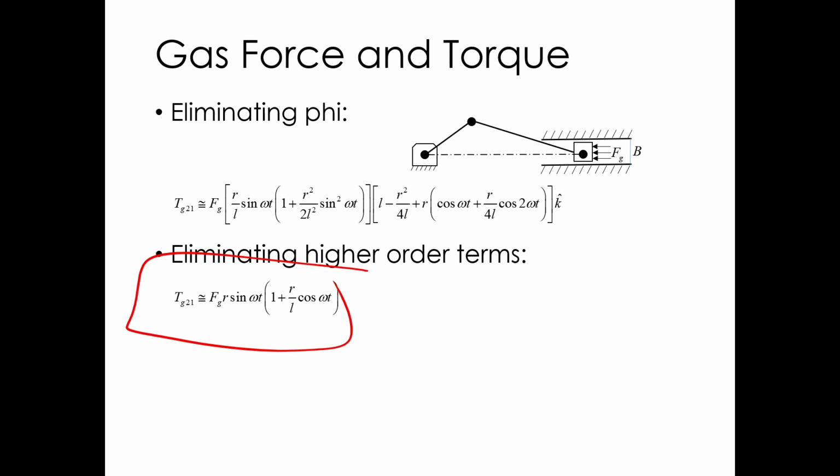So at this point in time, if you want to do a better job, rather than trying to keep refining this approach, go back to force analysis for a crank slider engine and the equations we derived there, and you can use that to create a really good free body diagram based model where you can include anything you want to include. You can include the center of mass of the crank. You can include the center of mass of the connecting rod. In fact, that's what you did in your project, right? So you can take what you did in the project and extend that for 0 degrees, 10 degrees, 20 degrees, or 1 degree or 10th degree increments, and you can make a total simulation of an engine that includes all the stuff that we're neglecting in this model.